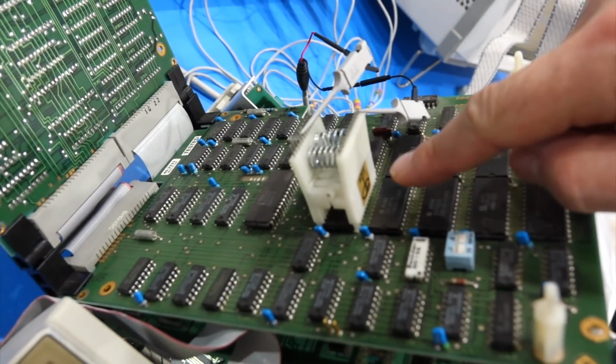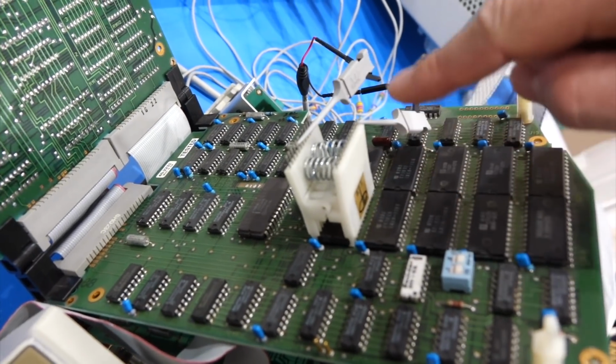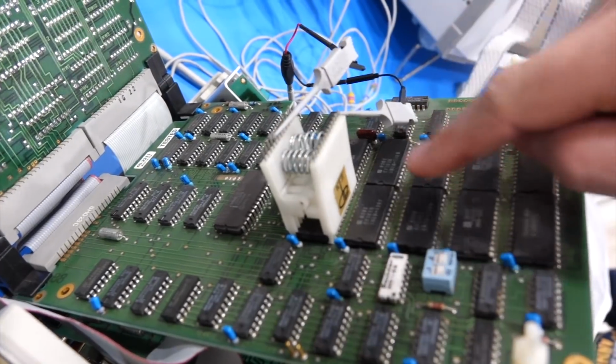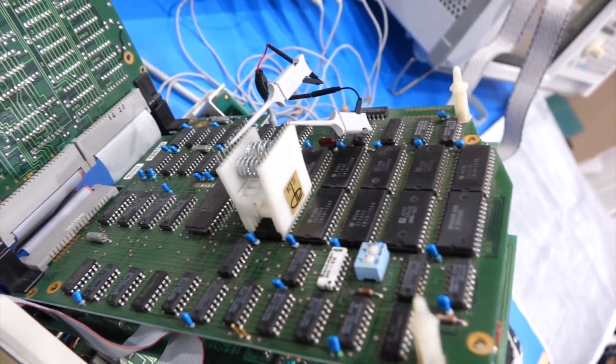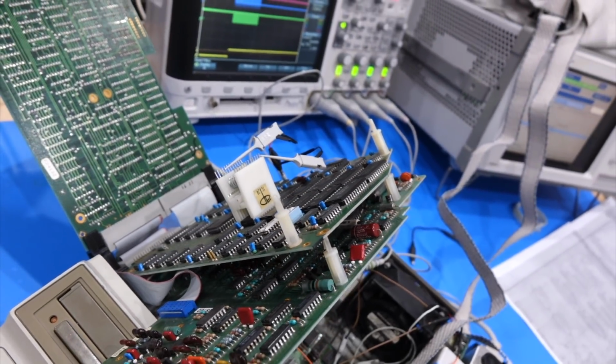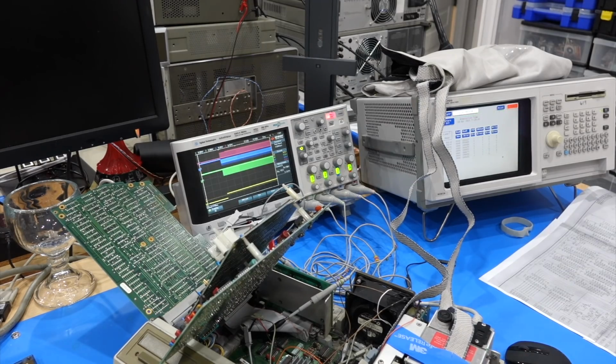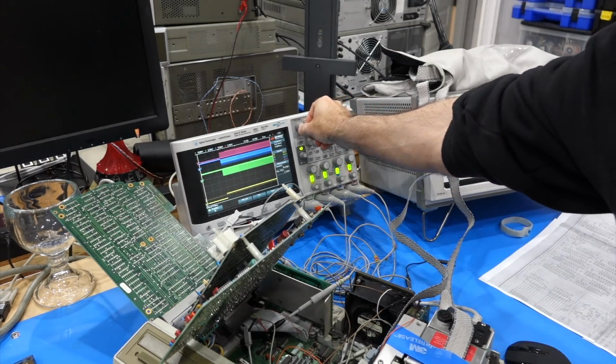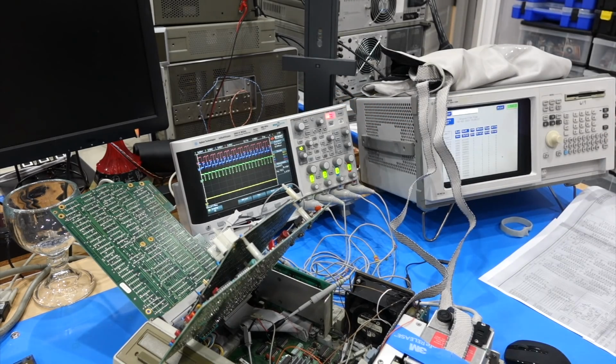Correct. So here are my ROM chips. This is the bank 0. And I am on ground and select, so that chip would be selected to read the code to do the startup, and it doesn't read anything, so we'll see. Yeah, it sure selected. I mean, it's selected. It should have read what's in location 40. We didn't get it out of the ROM. That's right. So now the issue is what's coming out of the ROM.